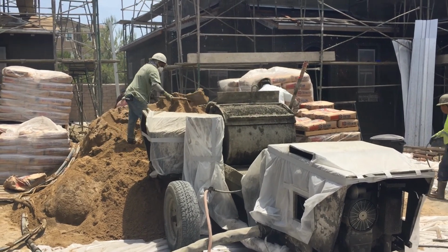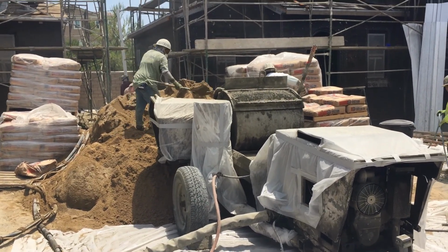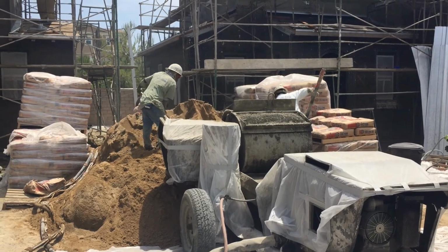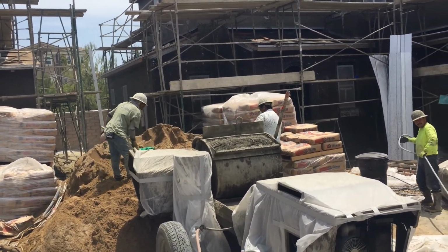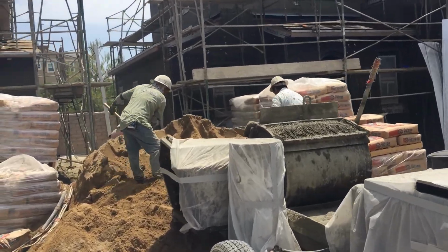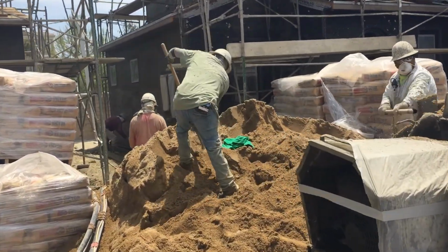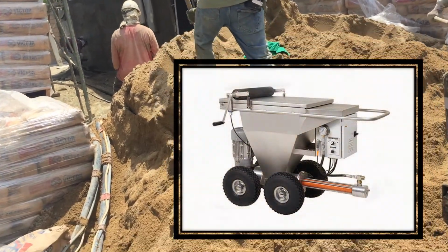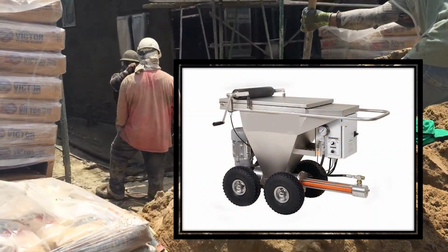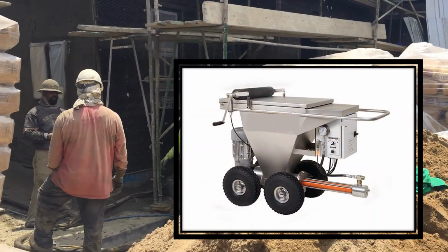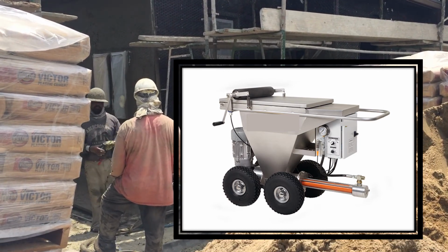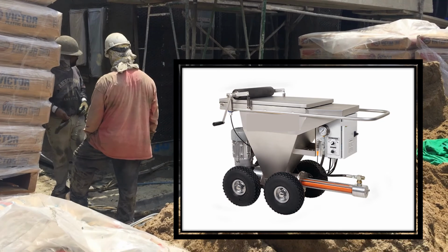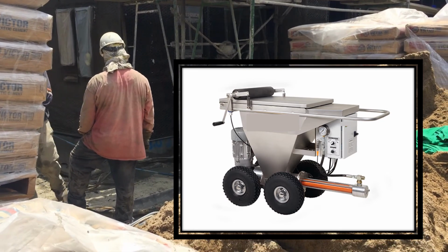Most are 4-cylinder machines capable of pumping over 200 bags of cement blended with 50 tons of sand. Crew sizes typically range from 7 to 11 workers. Smaller machines are available and only require 2 or 3 workers. They're excellent for faster production rates than hand tool work, but do not require the larger volumes of work or large size crews of the big machines.